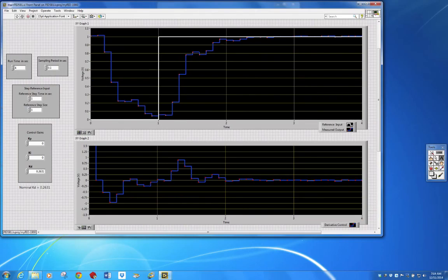Looking at these results though, you might be wondering just how much slower can we go in terms of sampling rate before we start to run into trouble. You hopefully recall from our earlier discussion that for our analog plant here with its vibration mode at 1 Hertz, to control that vibration mode, the absolute minimum sampling rate required was 2 samples per second. You're looking here at closed loop control at 10 samples per second. What if we cut the sampling rate in half again? Well, I don't want to spoil all your fun here, so I'm going to leave that bit of experimenting up to you to do on your own.